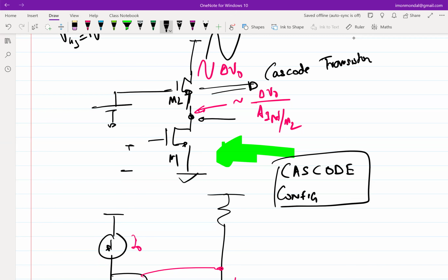So the amount of current that exits from M1, this current, okay, let me rephrase that. Essentially, in case of a common source amplifier, the job of the cascode transistor is to shield the swing. It should put a shield between RL and M1 in such a way that all the incremental current from M1 goes into RL, right? And not into its own